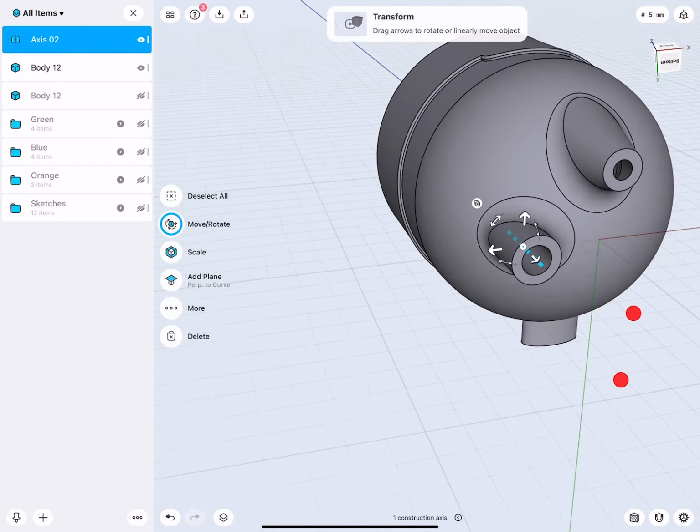Let me go to the top view. And you see actually right there, this is where the spline ends. And when we go to a side view, this is actually important to point out, you see how initially the sketch also terminates on a grid. The reason why I'm pointing this out is when this is my axis, it is very easy in this top view then to see where it is and simply draw myself a circle that is right aligned to the grid. And in this way, that's simply how I managed to create a circle that is kind of centered on this line.